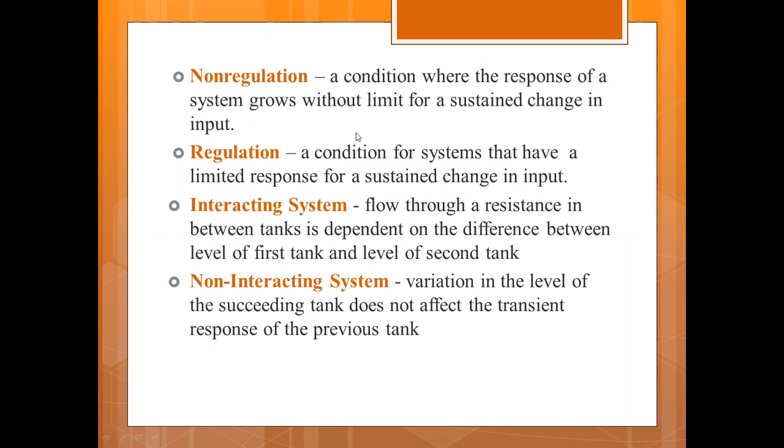We don't say, as is the usual case, that the previous tank is loading the second tank. But in the case of an interacting system, it's actually the next tank that is said to be loading the first. So it affects the response of the previous tank.